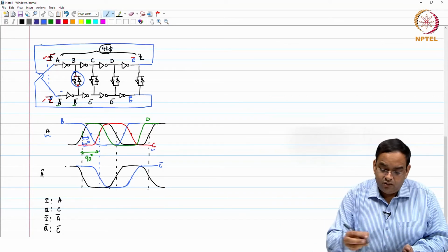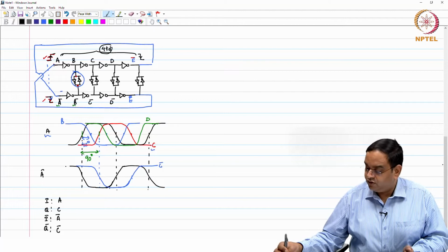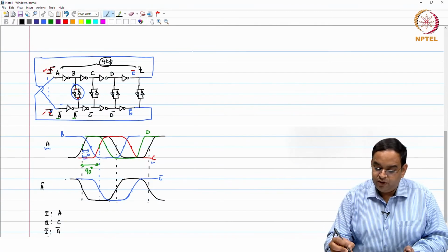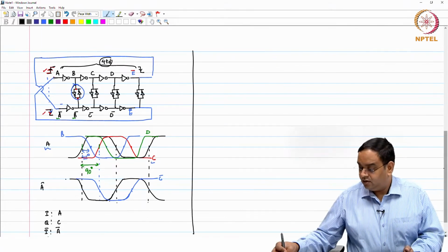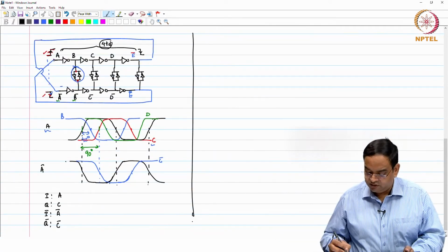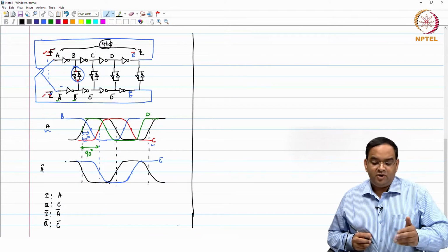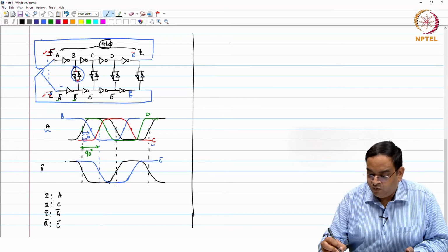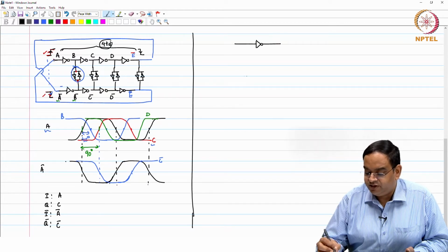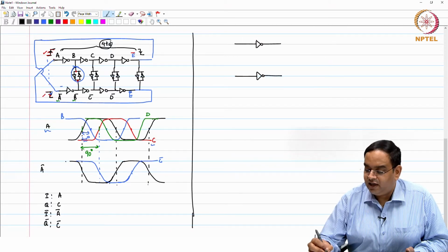Okay. So, now given this, the question always is how you are going to size these inverters for the pseudo differential ring oscillator. Okay. So, whenever we want an even number of phases, we can do so. Now, I will just take one cell or one part of this pseudo differential ring oscillator, because that is something which is repeated, and I have this cross coupled inverter.